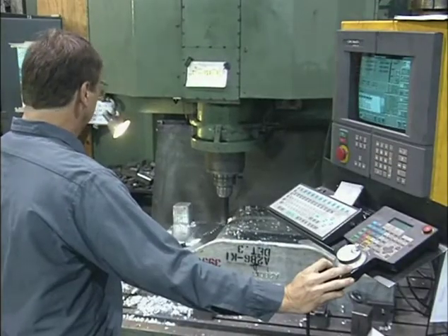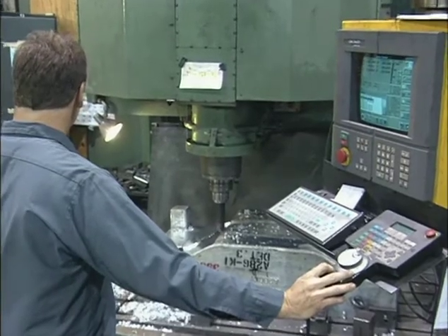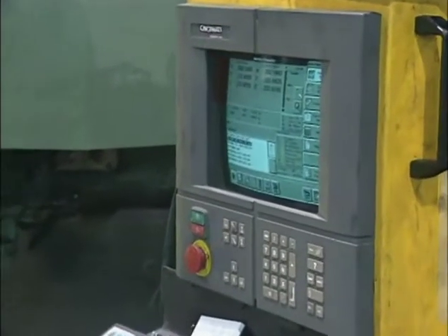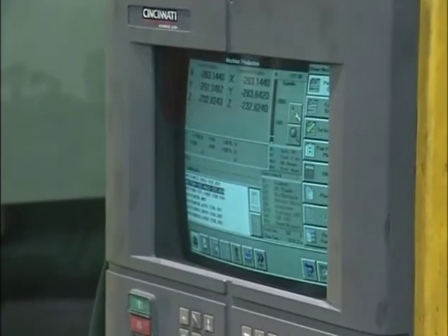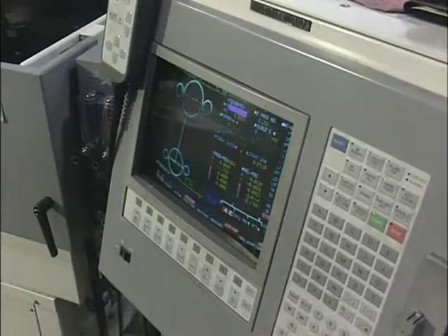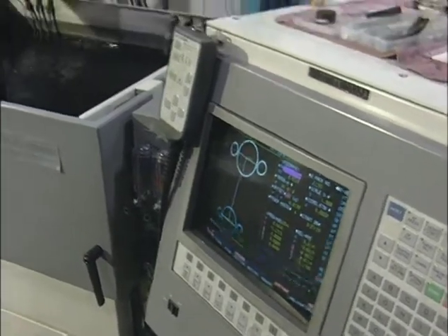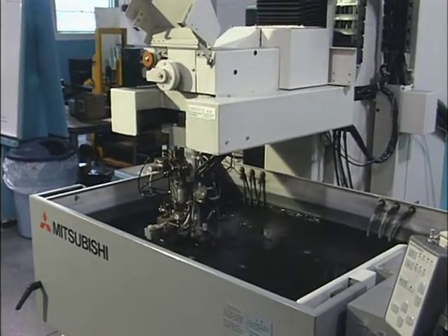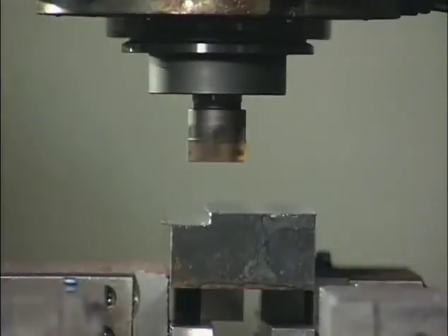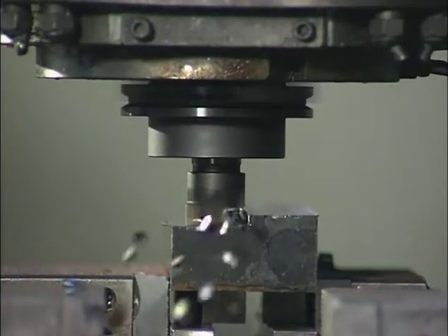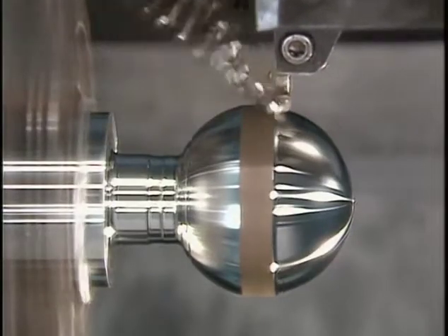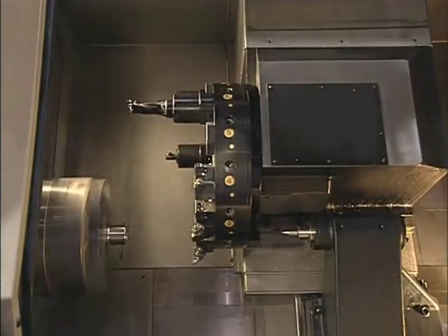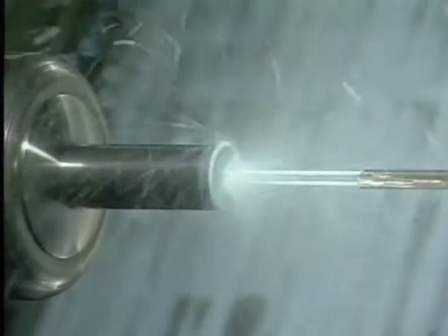Computer numerical control, or CNC, built upon the standard numerical control production capabilities by incorporating an integral computer processor to govern the machine controls. Programmed instructions, or data, in the form of a part program is translated by the machine control into output signals that control machine functions, such as spindle rotation, cutting tool movement, workpiece movement, tool changing, and cutting fluid control.